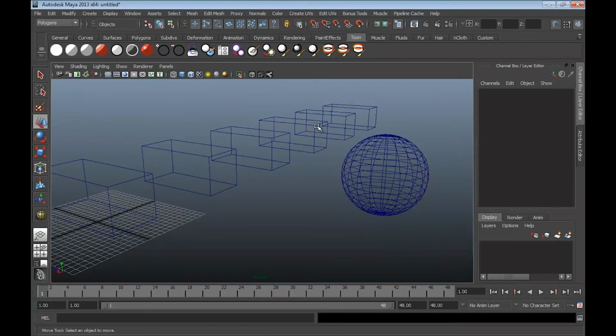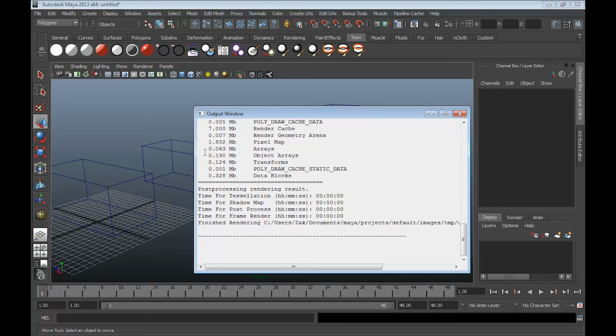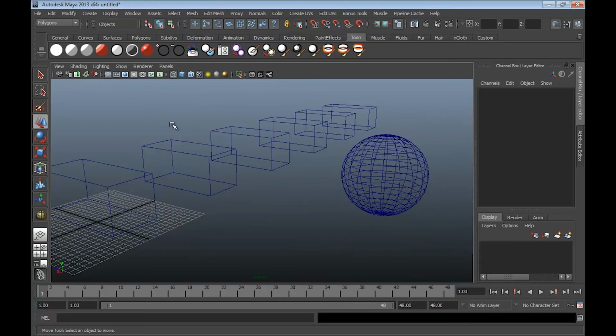Now, somebody just asked a question. Please try to keep official questions over in the questions section of the webinar, but I did just happen to notice this. Is the output window important? It opens every time I open Maya, and it will. It always will. Really, for the most part, and for our purposes, you'll probably never really need the output window. The output window is really nice, though, if you're trying to monitor a render and see at what point Maya is crashing, or look for feedback from a script or things like that. But for our purposes, we won't really need it.